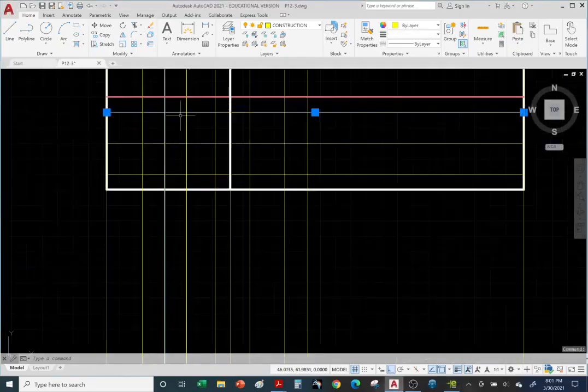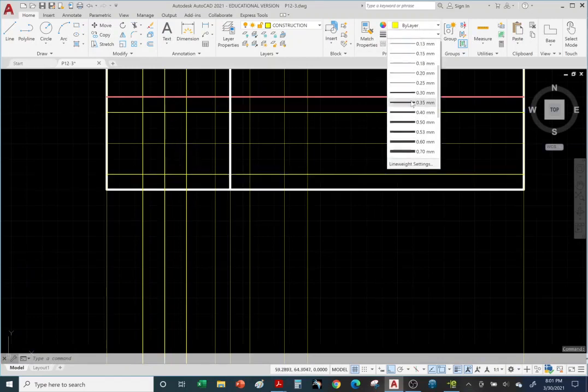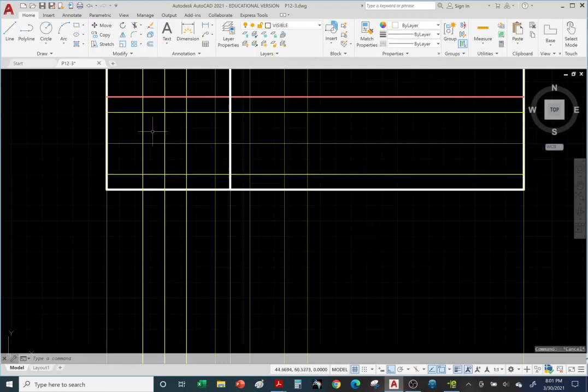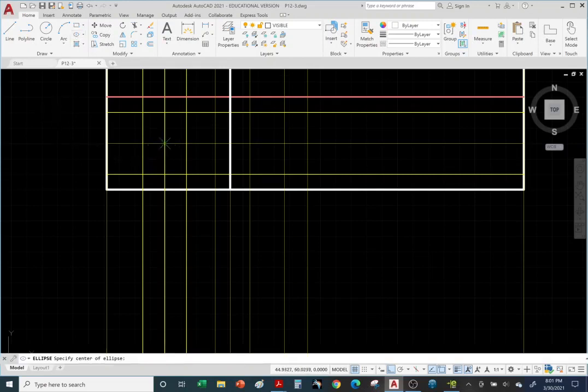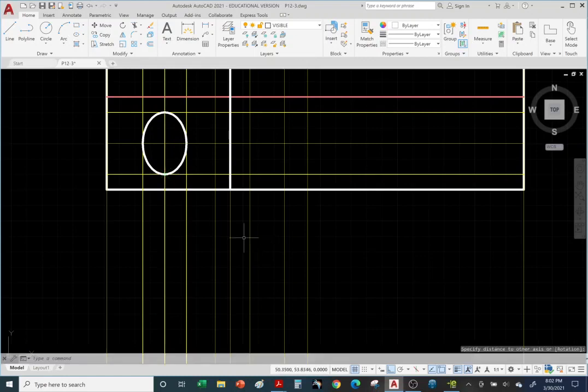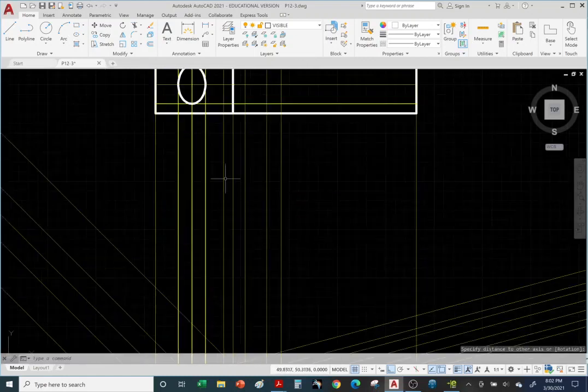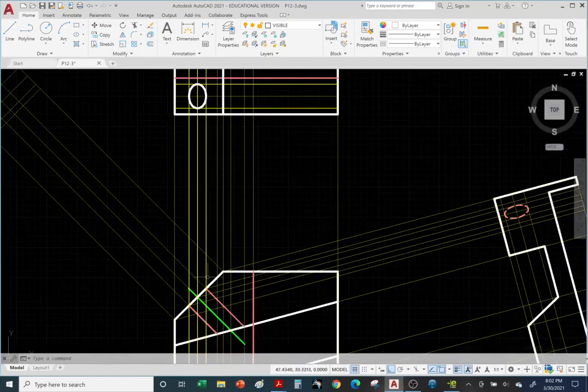We're going to use this construction line and this one for our quadrants. Let me thicken those so they stand out. Hit escape to deselect. Here is our area for the ellipse. Let's go to the visible layer and use the ellipse command. Ellipse. Here is the center mark, and we can go to right quadrant or left quadrant, and then the top or lower quadrant, either one will work. And there's the ellipse, ta-da, right? And notice how it lines up with the hole in the front view.